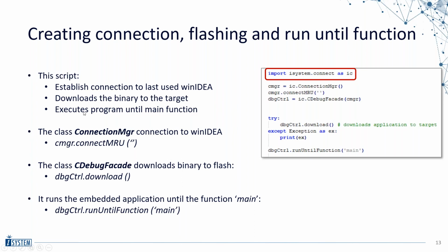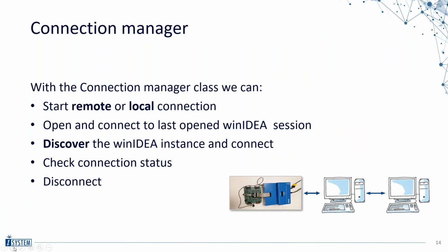So basically, I have already explained the connection manager. We connect to the last open winIDEA. Then with the debug facade, we flash the binary, and then we run until main. Okay, next slide. Connection manager.